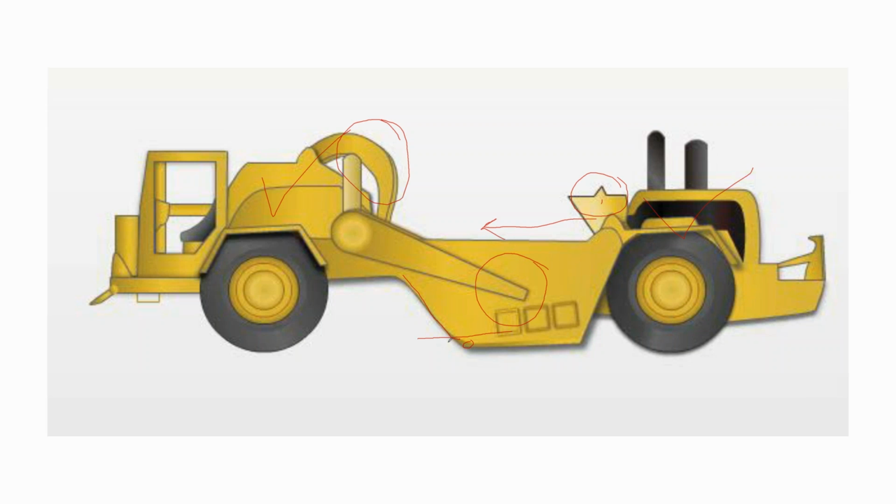The soil is at this elevation. The soil comes and boils in and fills the bowl up. We then raise the bowl so that it's sitting above the pavement or above the surface being cut. Could be pavement, it'll cut that too. Roll along, and then when it gets to the point of discharge, it opens the apron a little bit. It has a distance from the bottom of the bowl to the area where the fill is occurring, and this ejector pushes out in this direction, and we put out a layer of soil. And if you recall, when we talked about compaction, we talked about the thickness of this layer that was required to get compaction, and this is how we control it.